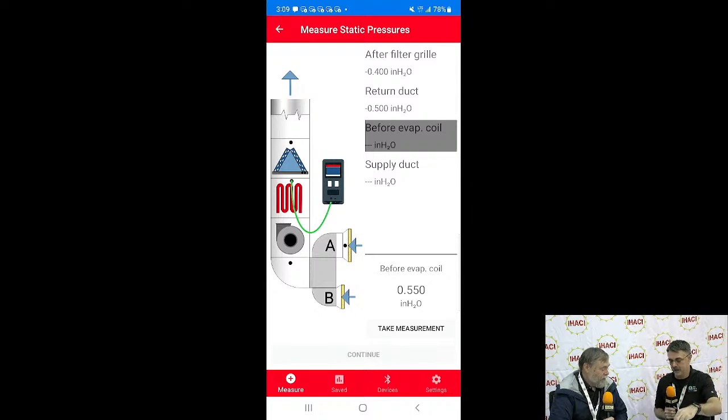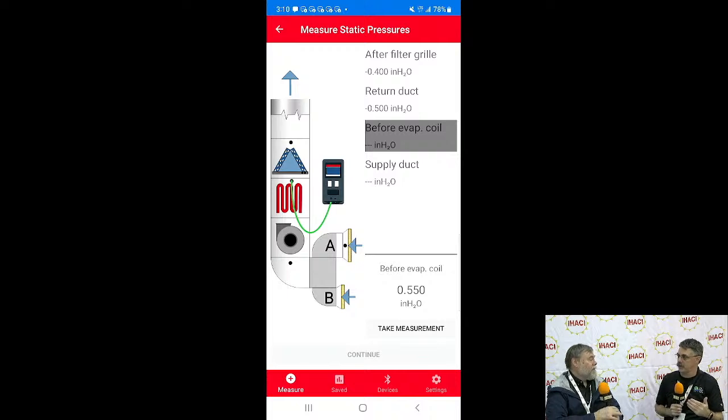The cool thing about this DG8, if you haven't used one of these, is that it uses the same sensors that a blower door manometer does. So it's basically a DG700 or DG1000 converted into a more simple, single channel with dual ports. But it has that auto zeroing feature. There's a little valve in there that auto zeros, so you don't have to keep hitting zero.